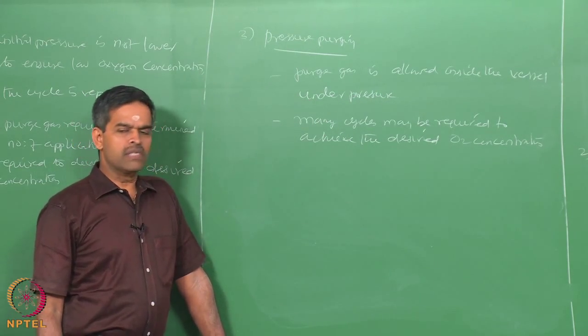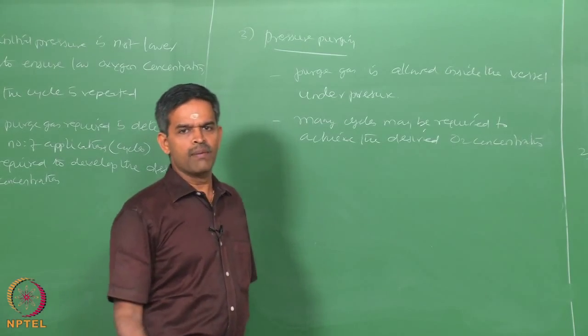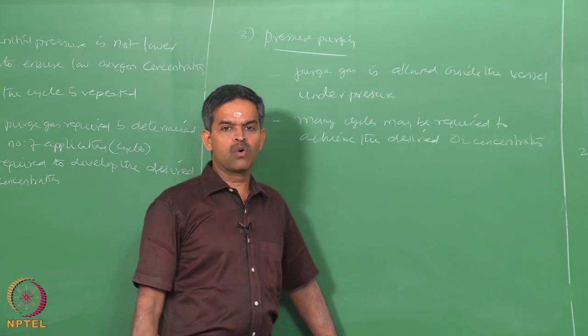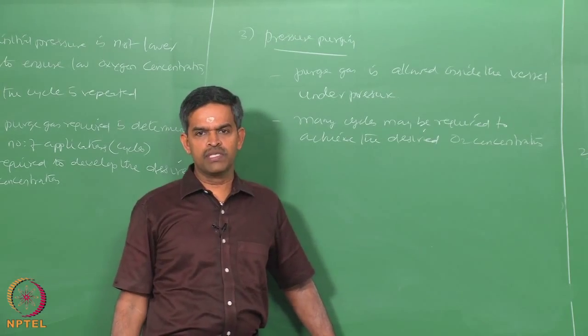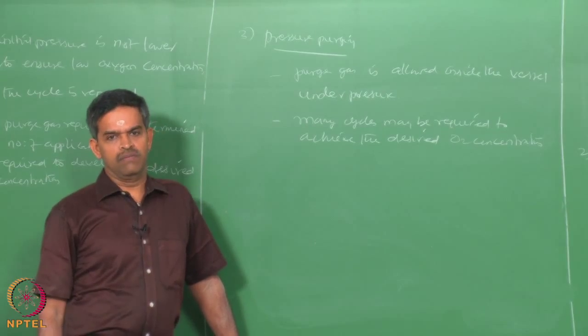When two or more containers or tanks are to be purged in parallel, or when they are joined by a manifold, and if they need to be purged together as a group, then the vapor content of each container should be checked so that the desired purging pressure is achieved.